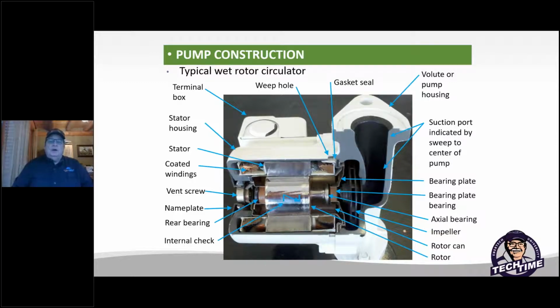Bear in mind, the one thing that I also learned is that these pumps that we sell from GeoFlow and other manufacturers have a special coating on the electrical wires so that they're more damp proof and waterproof for cold water chilled systems. The red ones or other ones that you could buy don't have that absolute protection in them, and maybe that's sometimes why we see premature failures with those. So keep in mind, there's a reason why we sell the pumps that we do. These are designed for cold water applications and for better protection.